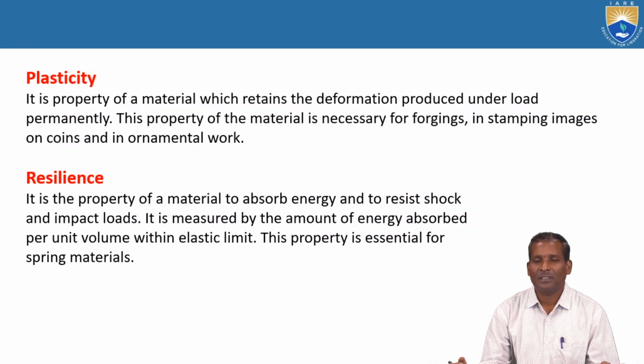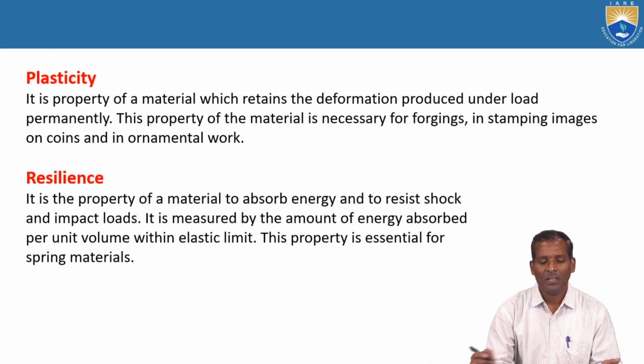Sometimes the plasticity property is useful for operations like forging, stamping images and coins, and ornamental works. That is useful deformation. Whenever the load is removed, the component will not regain its original shape. The property is called plasticity.